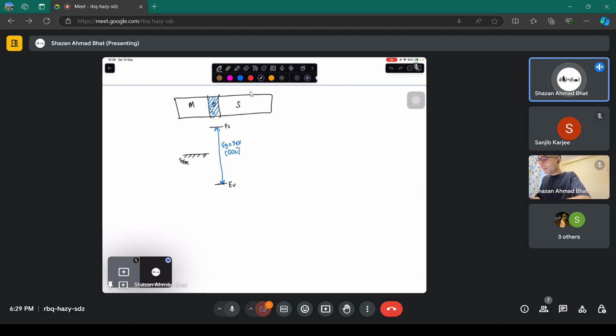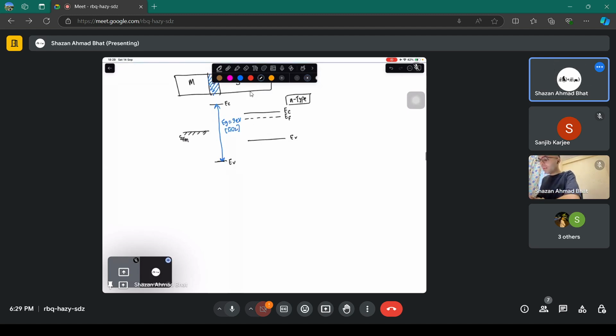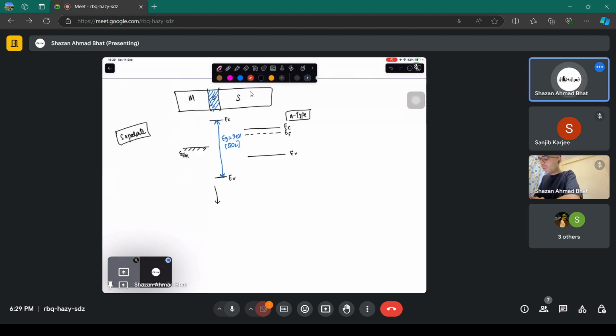Now for the semiconductor, you have a conduction band, you have a valence band, and let's say if you consider this as an n-type semiconductor for the time being, then this is the Fermi level of this particular semiconductor. Now this is when all of them are separate, not combined. Okay, and you consider a common level of energy, which is the vacuum level, which is the energy required to make the electrons totally free from the force present inside the crystal.